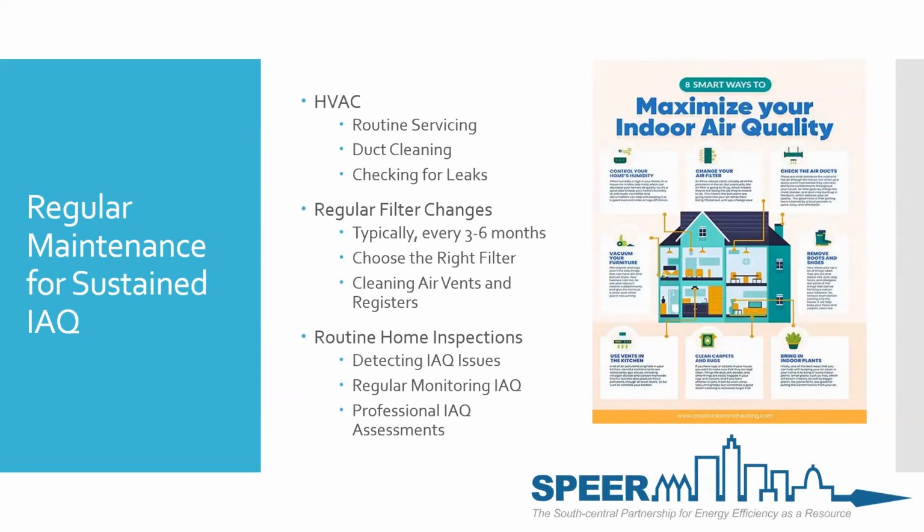It could be every 3 months. It could be every 6 months. It used to be, when I had this house built in '94, every 30 days. We had a 1-inch filter, and you did it every 30 days. But I was a homeowner that didn't know anything, and I went out there and bought the highest and most expensive 1-inch filter I could with the highest MERV rating. I've now changed my system. The system did not fail on me, but it could have, just due to the fact that it was too high of a MERV for that system. So choosing the right filter is also very important.